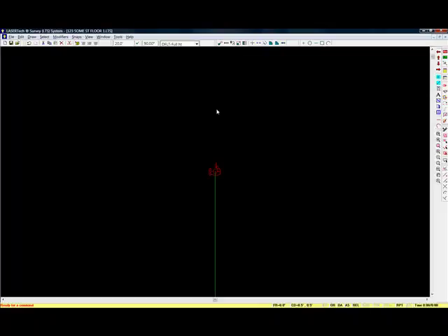I would then turn right, and there's a button on the disto. The operator would actually be hitting the right arrow on the disto, and that would be turning our surveyor. We're assuming this is a square room. We look at it, and we can tell it's square. We would enter the measurement and say it's 25 feet, and then we would turn our surveyor to the right, and we disto the next distance.